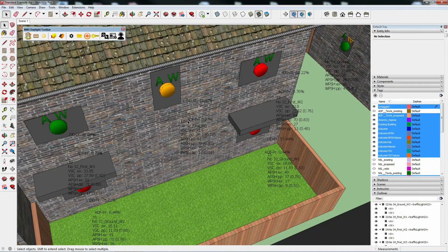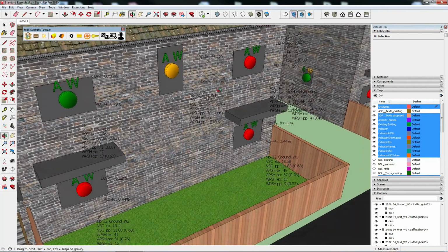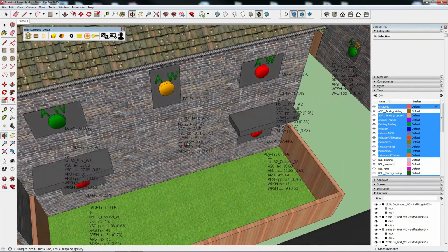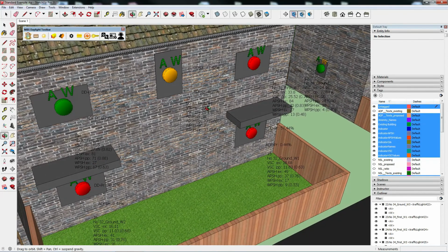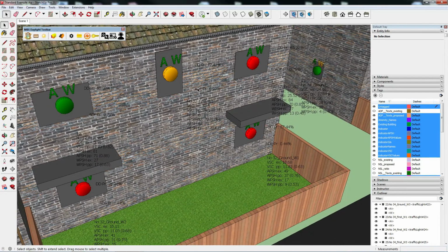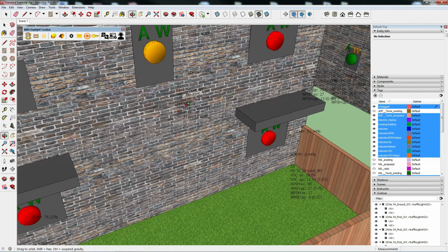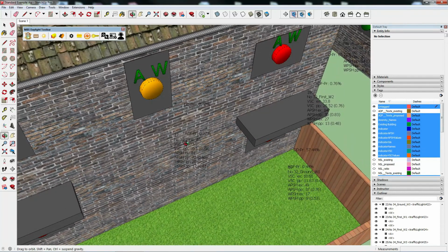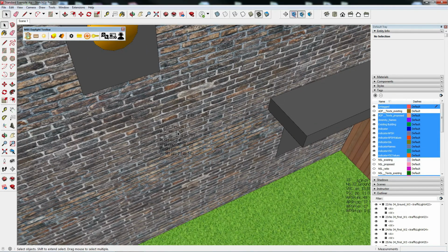If you need to look at these results in a little bit more detail, you can. And you can see we've got the room calculations there as well, the no skyline, the average daylight factor. We've also got our window calculations. So we've got the VSC values, existing and proposed, and then the ratio, 0.78. So you can see this is pretty close to passing, which is why this one's yellow. We've also got annual probable sunlight hours, existing, proposed, and the ratio, and the same again for winter.